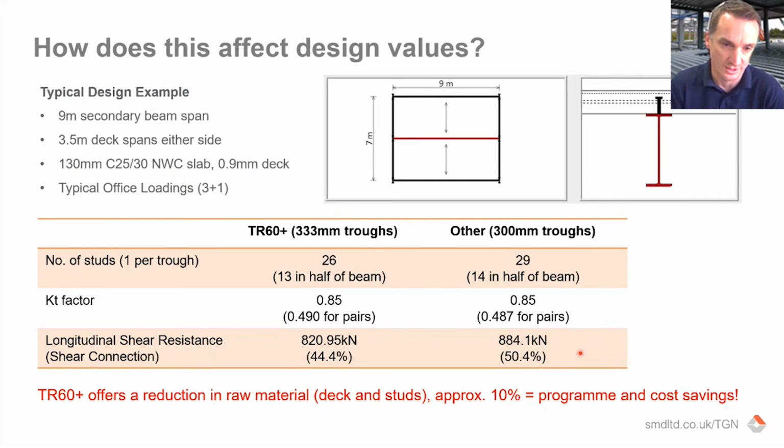But as I said earlier, it may well be that beam only requires this requirement. And by considering that, you're utilising less concrete, less raw material in the steel product itself. And that ultimately leads to some savings along the way, and also gives you flexibility should you need to change spec at the end. But it is just an important thing to realise for those who don't deal with decking every day like ourselves.